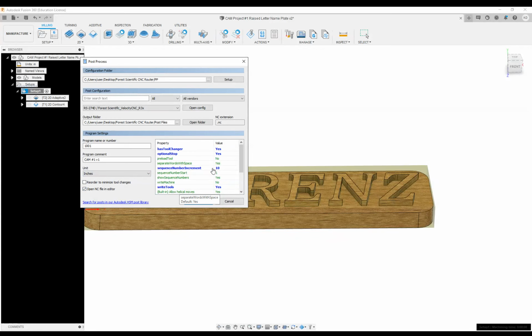For the G code sequence numbers, I prefer an increment of 10, starting at 1, so that if I need to make changes or additions to the G code, which I frequently do, there's space for it. By creating by tens, I can do 2 through 9 and have extra lines in there as well, without losing the number of my lines.